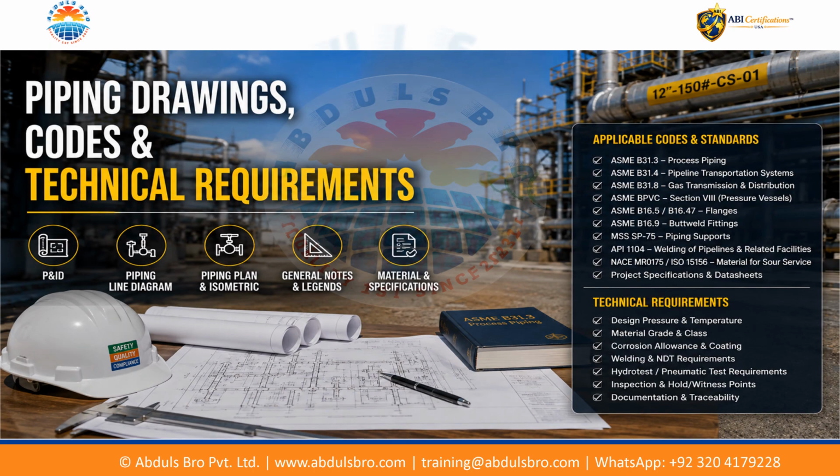Piping drawings, codes, and technical requirements. Effective piping QA/QC starts with the approved engineering and quality documentation. The inspection basis includes P&IDs, piping plans, applicable codes and standards, project specifications, piping classes, approved construction procedures, and the inspection and test plans. These documents establish the design requirements, inspection stages, and acceptance criteria. Before inspection, QA/QC personnel must verify the applicable document and current approved revision, ensuring that construction and inspection activities are performed against controlled project requirements.